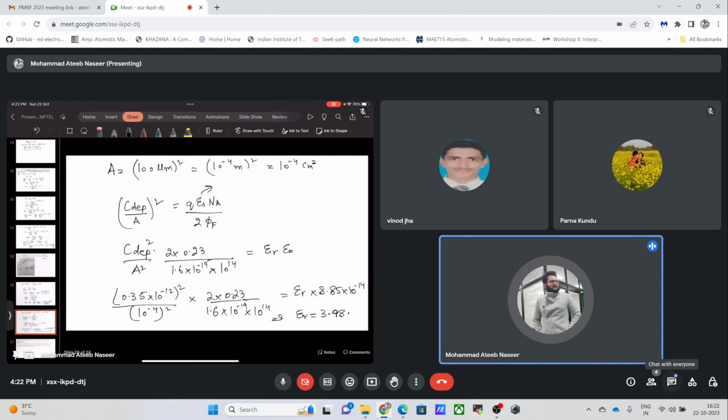We had seen how in the deep triode region this MOSFET will act as a resistor, and if we are going to use it as an amplifier, it is a voltage controlled current source, and how we will be biasing our MOSFET in the saturation region. For amplification purposes, we required this MOSFET to be operated in the saturation region. We wanted it to behave as a voltage controlled current source, where the input voltage was given at the VGS, and we do not want the output voltage to control this output current. We wanted this control to be minimal.